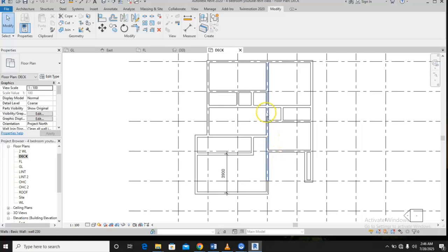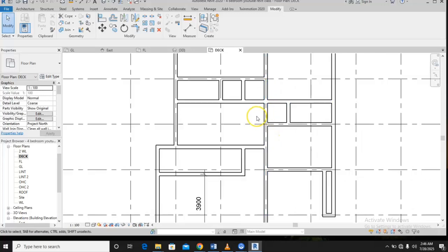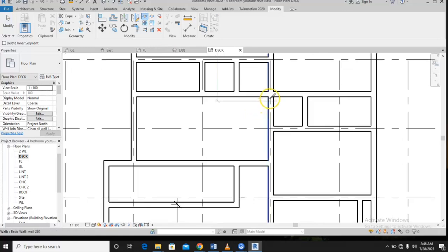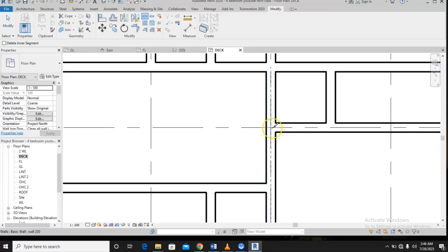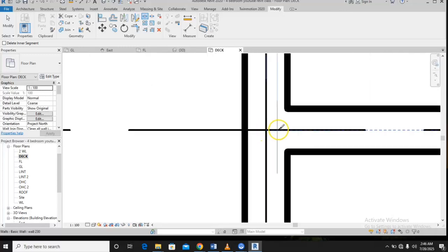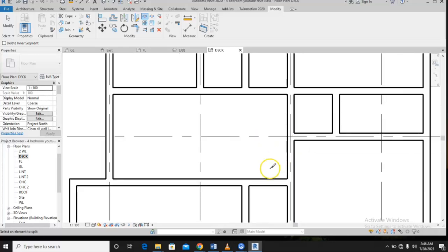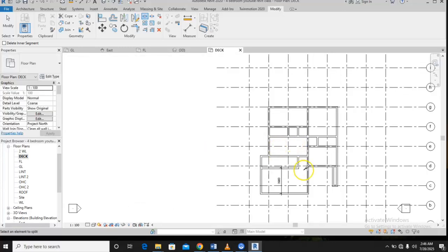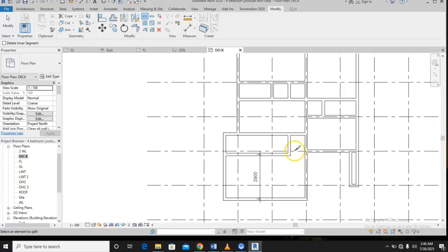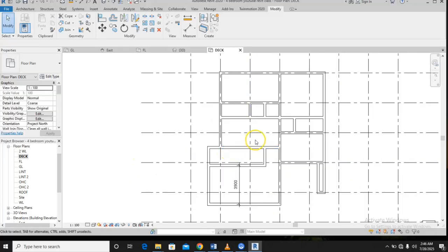Okay, so this one is locked, so you can click on this particular split, and then make sure you split them. And one thing with this duplex that you are seeing, you need to be very careful, because any wall you shift here or delete, it will affect the under or the top wall. So you need to be careful on which wall you are editing or touching. You understand, right?